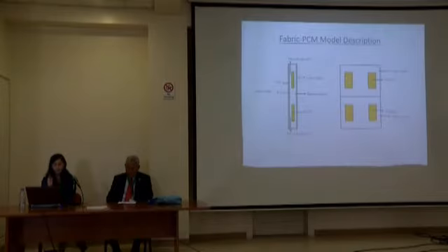It is important to not let the PCMs be in direct contact with the skin. And then there's a thin air layer. Then the PCMs, the non-uniform PCMs, are distributed. And then there's the outer fabric, but there's also another air layer separating the PCMs from the outer fabric. So I have to state the micro, or the air layers present here.